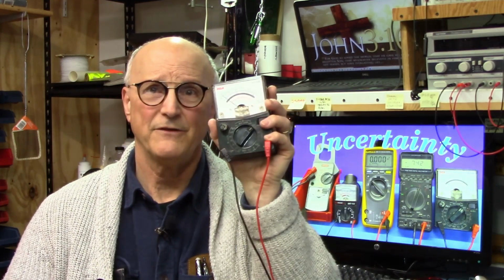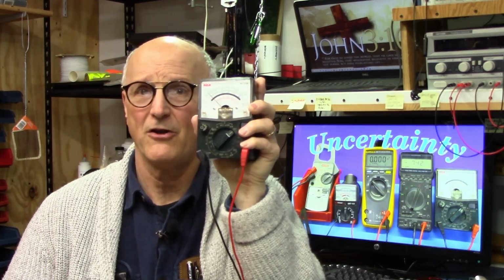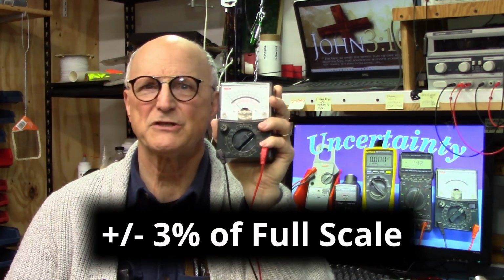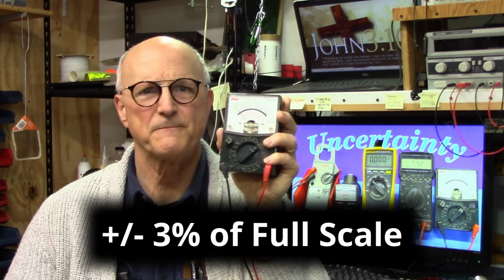The second one is just a little bit more obtuse. Not every measurement instrument rates its accuracy in terms of percentage of the reading itself. In many cases, it rates its accuracy in terms of its full scale reading. If I'm using this lovely vintage RCA WV518A analog multimeter, then the manufacturer's original specification is plus or minus 3% of full scale when measuring DC volts.